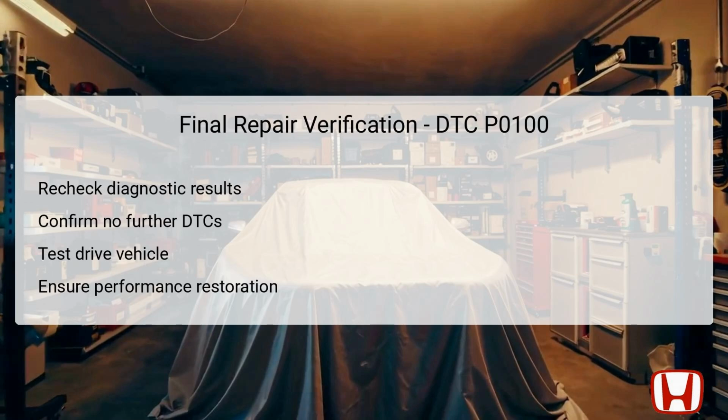The final repair verification step is crucial to ensure that the diagnostic and repair process was effective. Commence by rechecking all diagnostic results to confirm the resolution of code P0100. This involves running another scan with the HDS to ensure that no further DTCs are present.